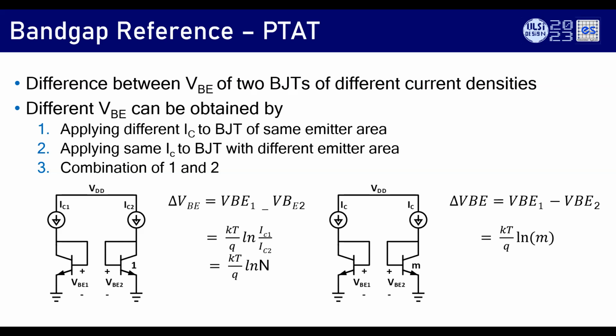Sizing of the BJT is chosen to be the most prominent one, simply because if you choose currents, the resistors involved in generating the PTAT tend to become big, and hence the area tends to be bulky. So typically, I have not seen people scaling the currents, unlike scaling of BJT diodes, simply because the resistors tend to be really big. Once the resistors are big, with leakage current and non-idealities, you get a lot more errors. Okay. I have seen some work where they use 1:2 current, maybe, not more than that. But the idea is the same. You just need to look for the current density.